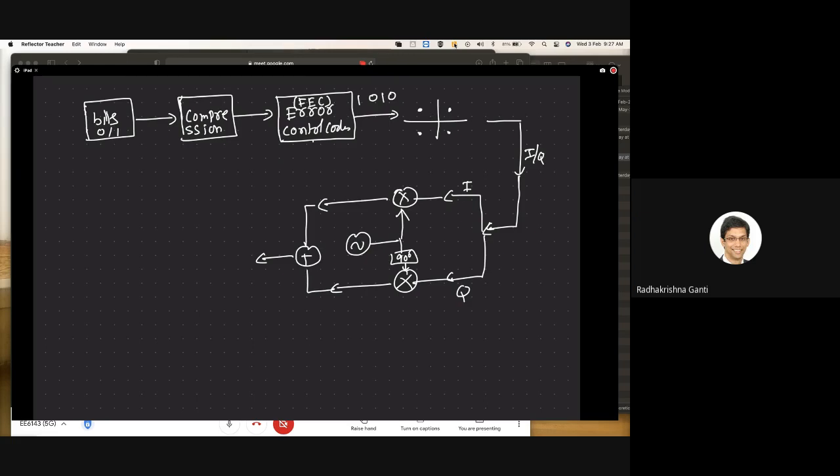Why do we assume all possibilities to be equiprobable? That's a very good question. So what does your FEC do? We make the assumption that the output of your FEC bits are equiprobable. Actually, it's not strictly true, but it's true with very high probability. The output of your compressor, if your compression is very good, will always be equiprobable.